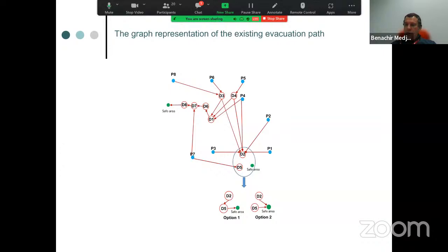The XY coordinates are a domain of possible values, and not a fixed value. This is what we did. Then, using an optimization model, we generated the location of these doors, minimizing the distances using constraint-based design. In fact, the distance of evacuation.